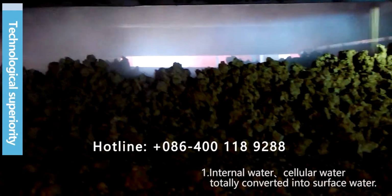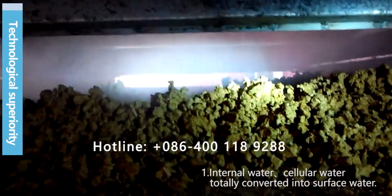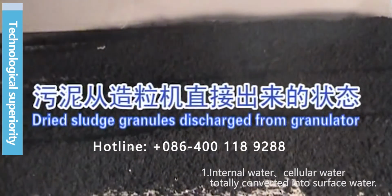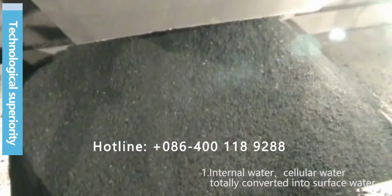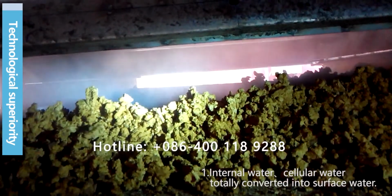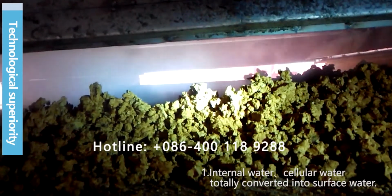The technical advantages. All water is on the porous particle surface. During the granulation process, the water inside the sludge moves to the particle's surface by breaking the particle wall repeatedly and continuously. The surface water is of course much easier to evaporate. The evaporation heat consumption is only 60% to 70% of the traditional dryer.